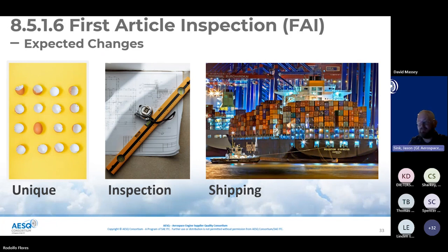Second, the exception for automated inspection processes, and the intent there is to actually provide the customer the option to provide exceptions for those automated inspection processes. And the third is the requirement to only release with a complete or not complete FAIR. So AS9102, as Klaus mentioned, removed the complete or not complete requirement and changed that with, are there any documented nonconformances within Form 1? And so this is really just an alignment to AS9102.